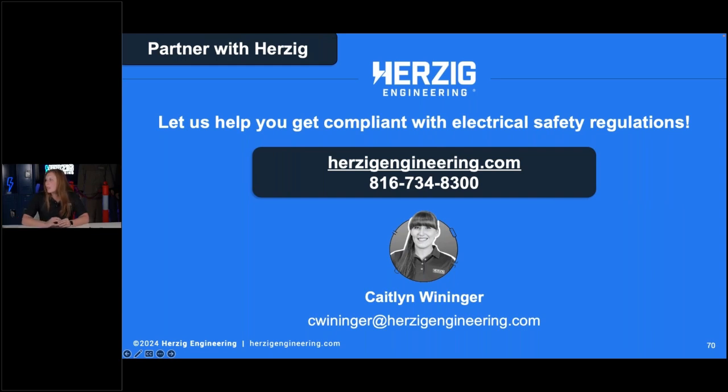Should anyone that takes LOTO training always take 70E training as well? Good question. It kind of goes hand in hand with my response to whether or not they need PPE. If they're ever going to have to put on electrical PPE, absolutely. They need to have that training specific to the 70E work practices as well. If they do not open anything that has electrical components, then they just need hazard awareness training, avoidance training, making sure that they don't accidentally open the wrong compartment.